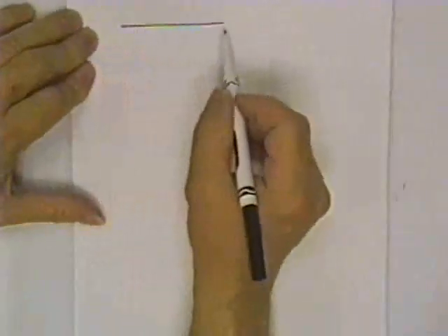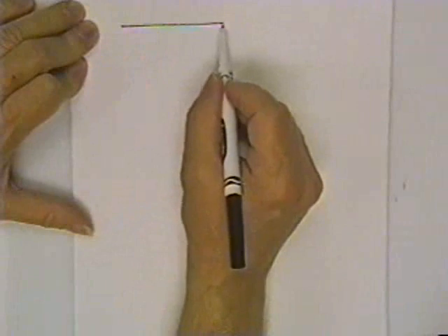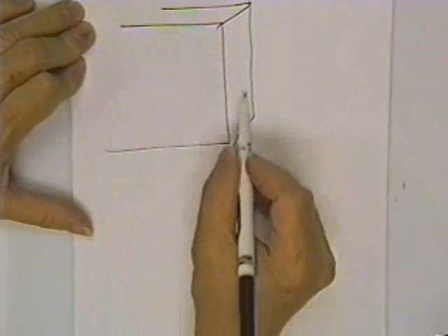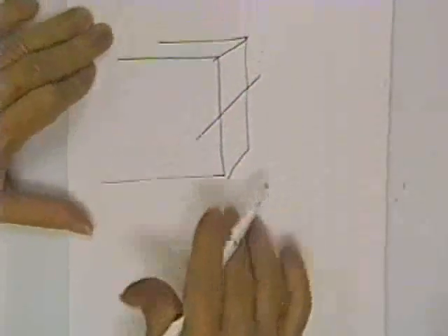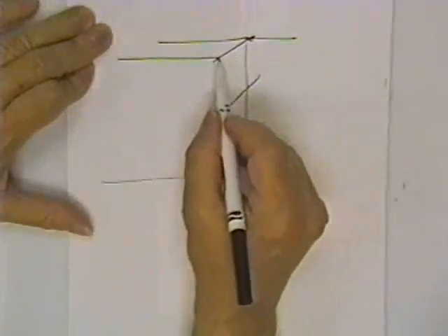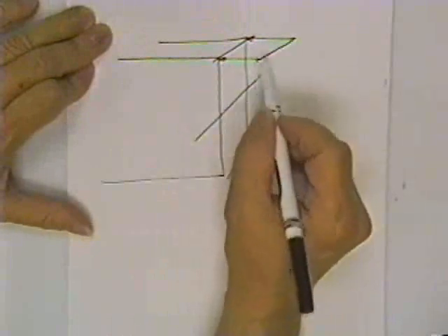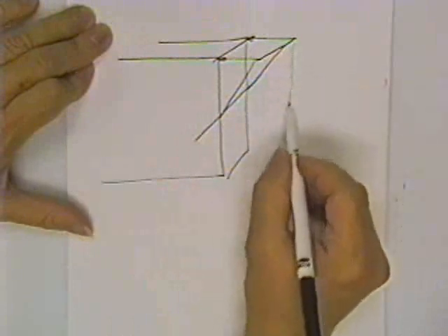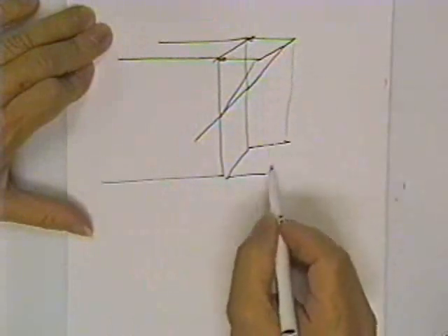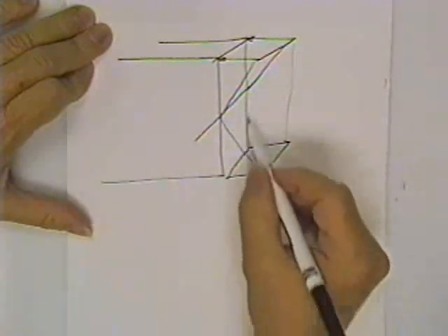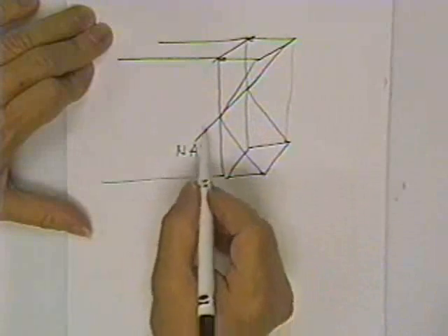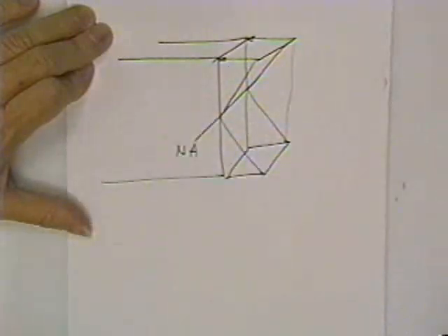I showed you in a beam, let's just say it's a rectangular beam, that that beam will normally have compressive stresses on one side of the beam, and they'll have tension stresses on the other side of the beam, and they are distributed linearly from the neutral axis. They are maximum on the outside fiber. They're zero at the neutral axis.